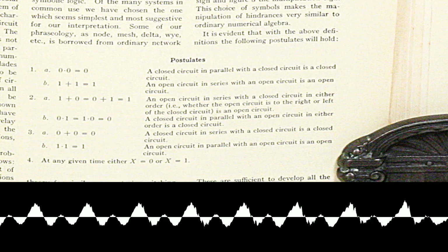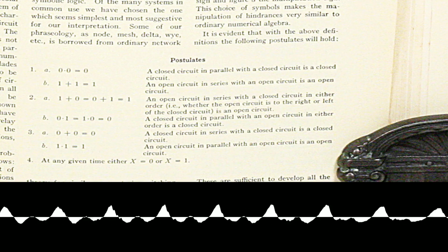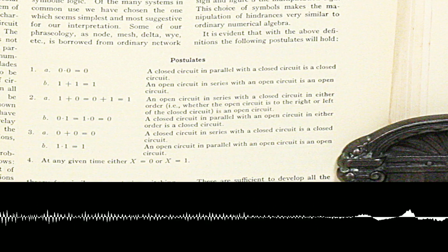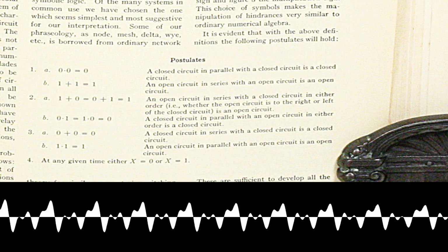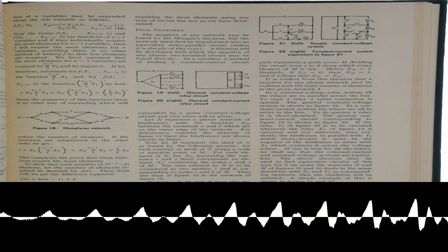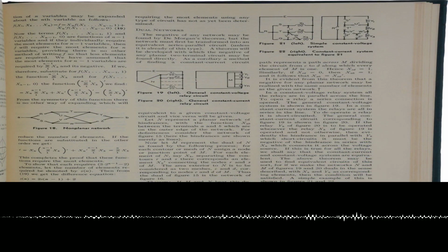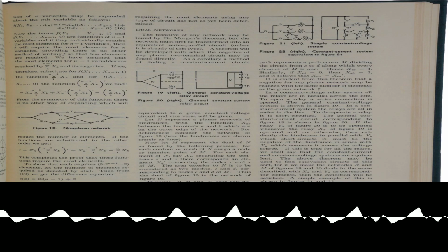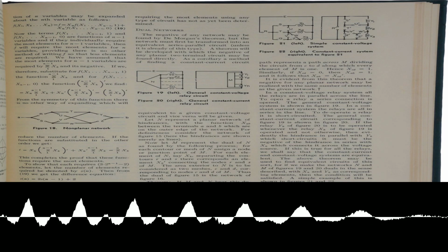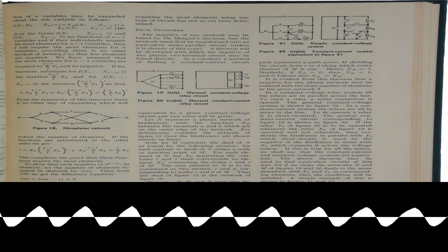Section 3: Boolean algebra as a tool for circuit simplification. Shannon illustrates the application of Boolean algebra for simplifying circuit structures. He explicitly identifies the laws and theorems of Boolean algebra: commutativity, associativity, distributivity, and the various axioms that can be employed to manipulate the algebraic expressions representing circuits. The central argument here is that these manipulations permit the reduction in the number of relays required to implement the same logical function. This signifies a path from a complex, potentially inefficient circuit to an equivalent, often simpler, one.